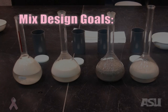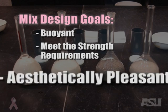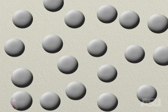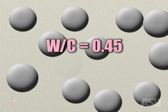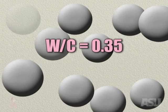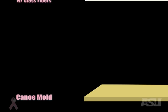The main goals for the mix design were to provide a concrete that would be buoyant, it would meet the strain requirements found by the structural analysis, and it would be aesthetically pleasant. To begin, increasing the particle size decreases the surface area that needs to be covered by the cement paste. This in part reduces water demand, yielding a lower water-to-cement ratio of 0.3, ultimately increasing strength.